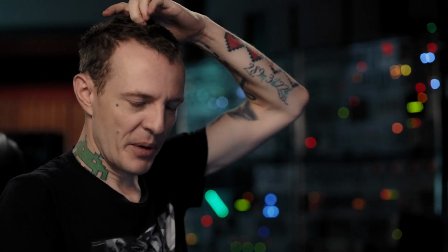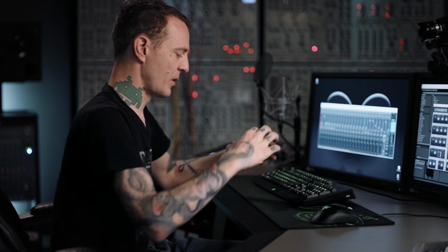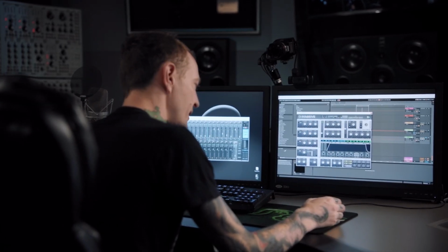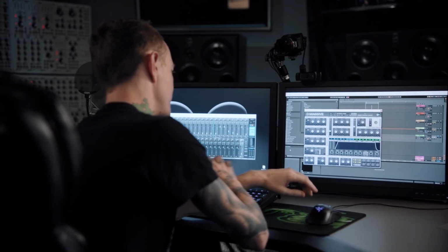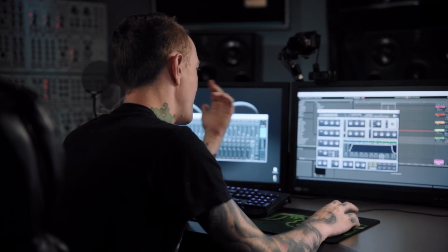So with the analog, there's no amount of steps. It's infinite. But with digital, you're obviously locked into certain increments of values due to the interpolation of the filter or the oversampling amount, which is basically the more oversampling, the more divisions it'll have within a filter step or an oscillator or something like that. That's what oversampling does. Some digital synths have oversampling that can come pretty close to recreating that, to the point where I wouldn't even be able to tell the difference, but then some don't and are so blatantly digital that you can hear it a mile away.